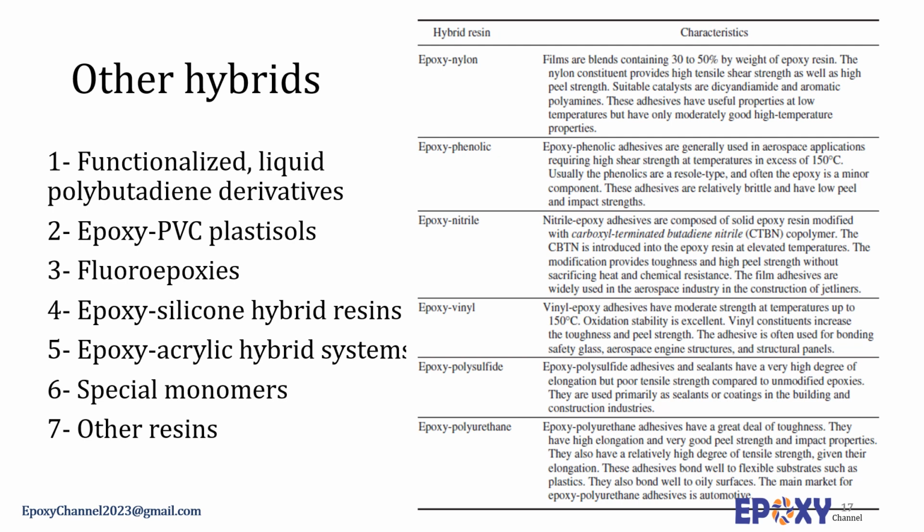Carboxyl-terminated butadiene acrylonitrile polymers, butadiene homopolymers, and maleic anhydride amino acid grafted butadiene homopolymers have been used as flexibilizers to impart good low temperature strain and water resistance to diglycidyl ether bisphenol A based epoxy adhesives. An epoxy system toughened by polybutadiene with maleic anhydride is claimed to provide a hydrophobic backbone, low viscosity, softness, and high tensile strain and adhesion.